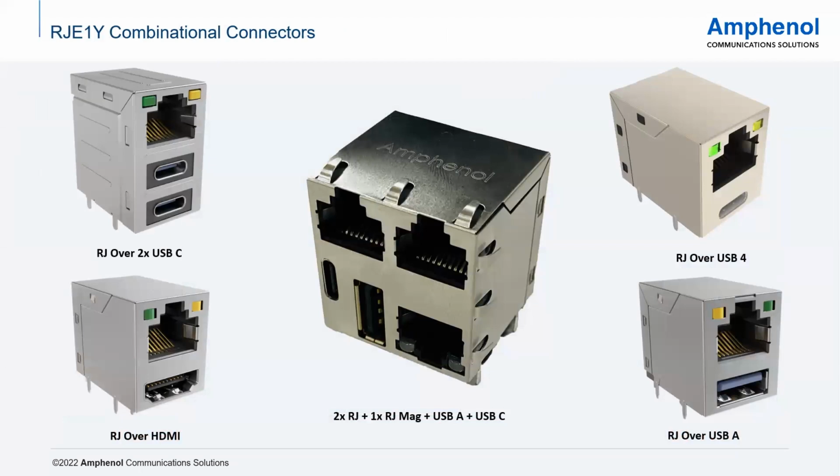Along with this, we have extended our portfolio with combinational connectors as well, with RJ playing a major role. Combinational connectors are mainly RJ along with a USB-C. It might be RJ over an HDMI, RJ over 2 USB-Cs, or the latest launch that we have, the 5-in-1 connector, wherein at the top you see 2 RJ connectors. At the bottom, the one with the LED is the RJ mag, and along with that, it comes with a USB-A and a USB-C.